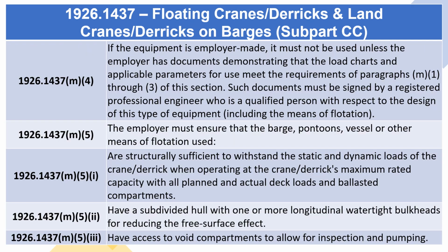1926.1437(M)(4). If the equipment is employer-made, it must not be used unless the employer has documents demonstrating that the load charts and applicable parameters for use meet the requirements of paragraphs (M)(1) through (3) of this section. Such documents must be signed by a registered professional engineer who is a qualified person with respect to the design of this type of equipment, including the means of flotation.